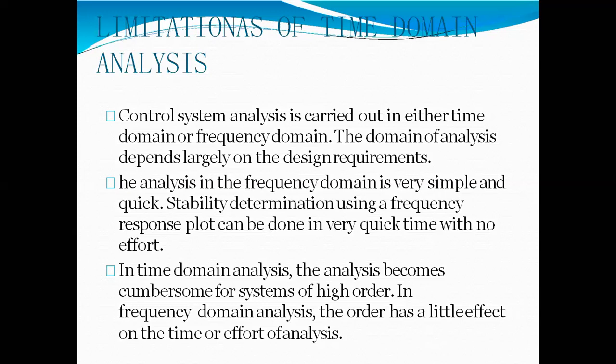The last says that in time domain analysis, the analysis becomes cumbersome. Cumbersome in the sense it becomes more difficult for systems of higher order. Higher order in the sense if my order is less, for example first order, it becomes a bit easy. If I increase the order by 1, 2, 3, 4, beyond that till n, then the time domain analysis becomes very difficult for the calculation. It becomes a very tough job for us to go for calculation in time domain. So that is the reason the frequency domain analysis is preferred compared to time domain.